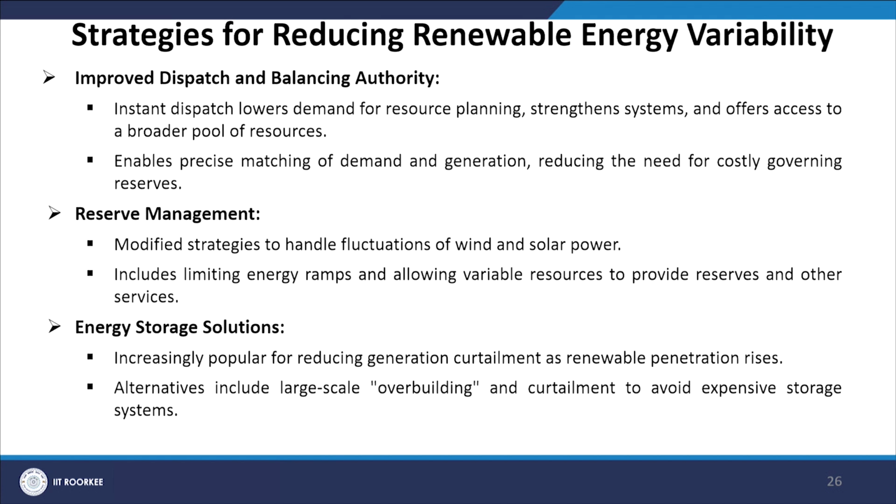Now, one more important issue is reserve management: modified strategies to handle fluctuations of wind and solar power, because how the excess power needs to be stored and managed becomes an important issue. This includes limiting energy ramps and allowing variable resources to provide reserves and other services.